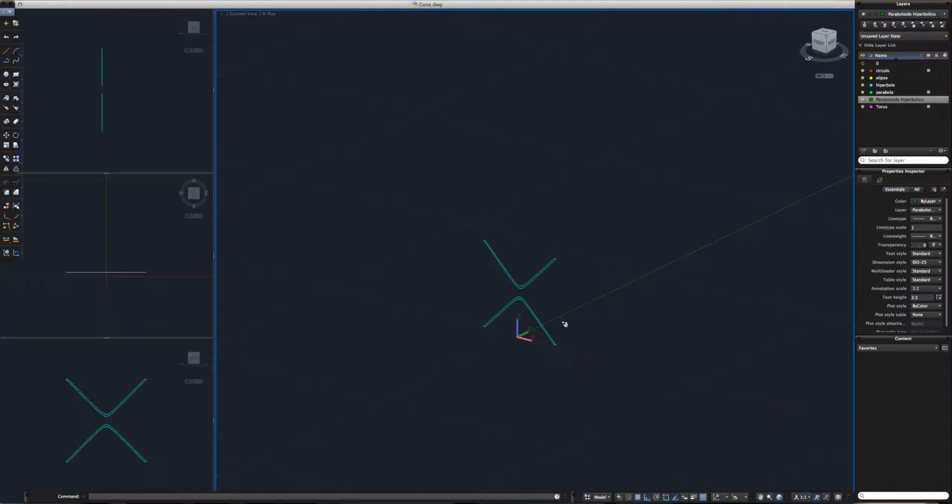Now, the idea here is to transform this into a hyperbolic paraboloid. This one is a bit trickier than the previous object we've worked with. So first off, we need to change our UCS. I'm going to do the same thing I did with our previous model. Select either this shape or this one, and select this one. Oh, my bad, missed it. Object, okay.